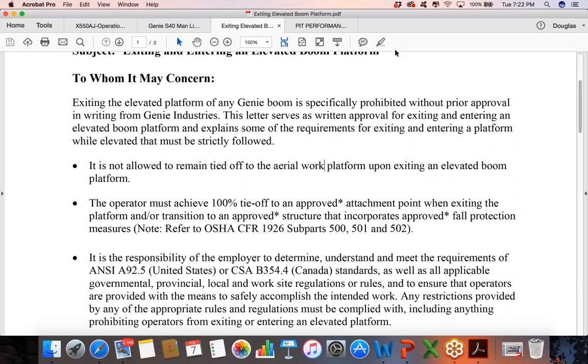So it's not acceptable to have an employee with tucked in work boots when they're doing steel erection or any type of hot work or work around chemical hazards. I tell employees all the time, best thing to do is always have those pant legs pulled out over the boot itself. Okay, pants with cuffs have to be avoided.